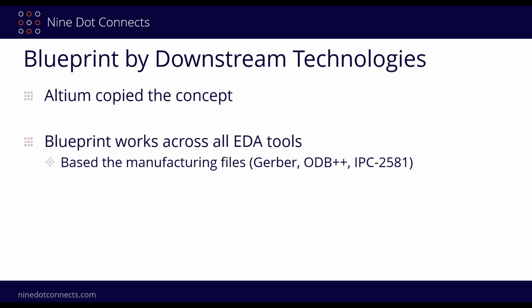Blueprint does work across all EDA tools, so it's all based on the manufacturing files, not their source files. So if you have Gerbers, ODB++, IPC, the NC drill files, all that stuff can get pulled into Blueprint, and they can effectively do what you saw here today.